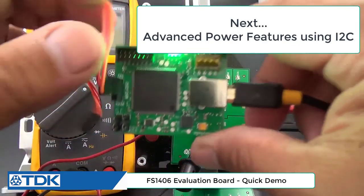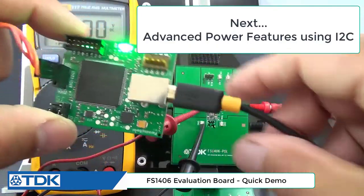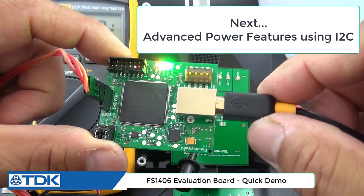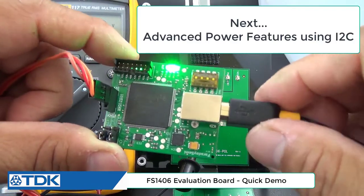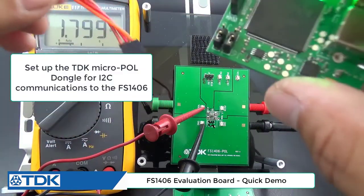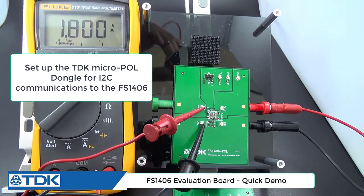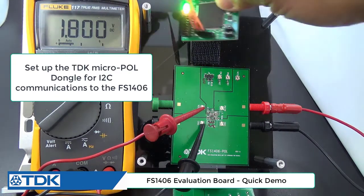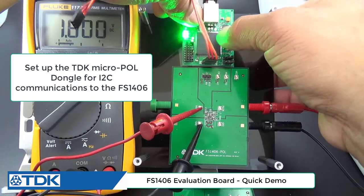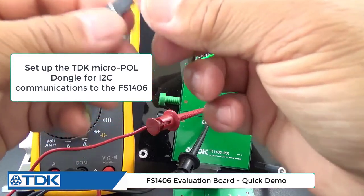This is actually the Faraday control center dongle. It's got the USB cable here to the right, which you would attach to your computer to access the control center GUI, and then the connector that goes on to the actual eval board. So let's go ahead and set this up very quickly for a fast demo of the control center GUI. And what we're going to do is change now this 1.8 volts to another voltage. We're going to demonstrate some of the simple I2C features.